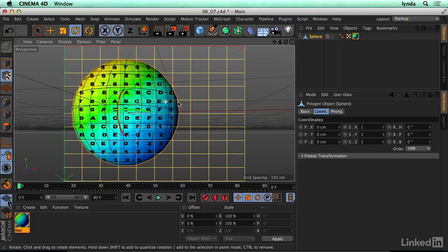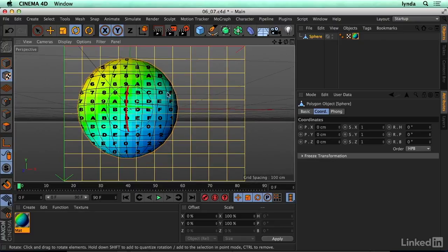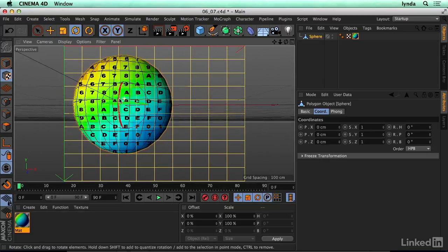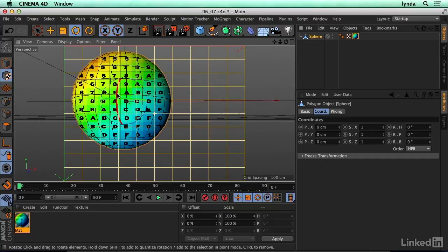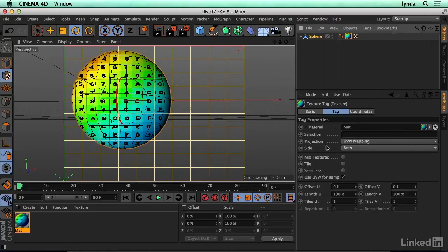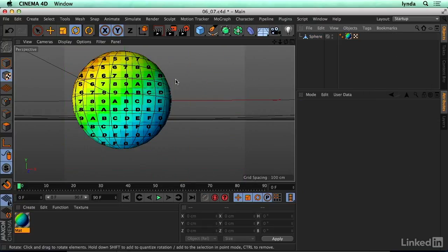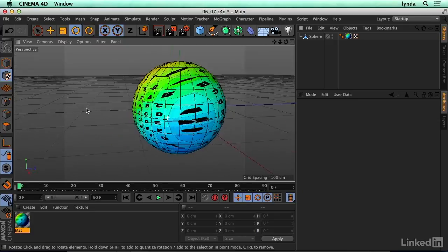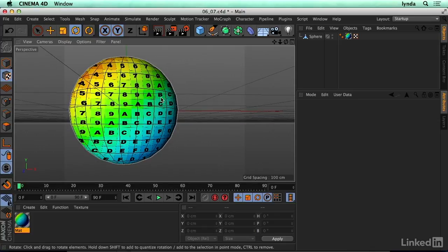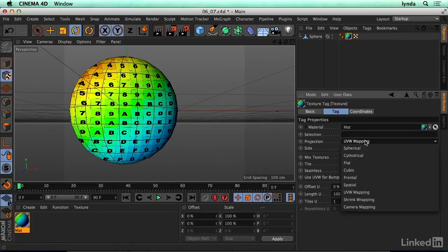Like if you wanted to park on an angle, let's say you're looking through a camera, matching it to a photograph or something. You can line this up and say, okay, right there is where I want that texture to live. And once you're happy with that, all you need to do, let's actually delete this UV tag, is say generate UV coordinates. Now it changes from a frontal projection into a UV projection. So no matter where we rotate, those coordinates are based on the camera, or the viewing angle, I should say, that we were using a couple moments ago. And at any point we can change this back.